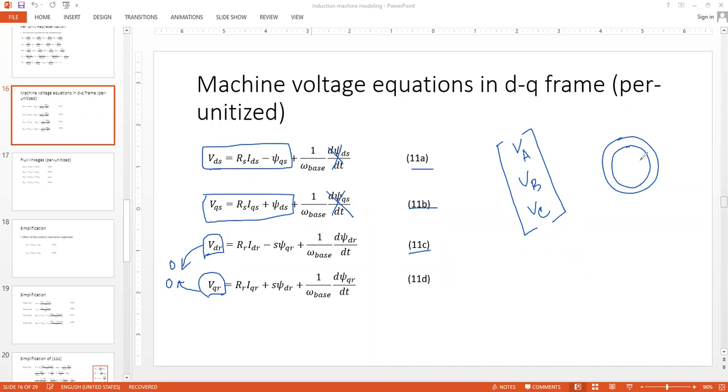In the rotor circuit, the rotor coils are short circuited so that you can have some rotor flux produced. You short out the coils either through resistors or directly. If it is a squirrel cage, by manufacturer it is shorted by end rings. If it is a wound rotor, then either you use resistors for starting torque control, or if you don't want that, then simply you have to short it.